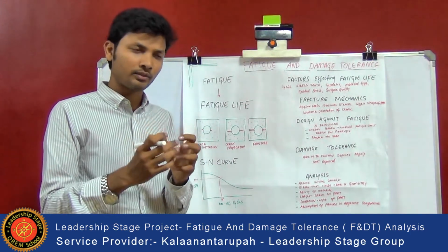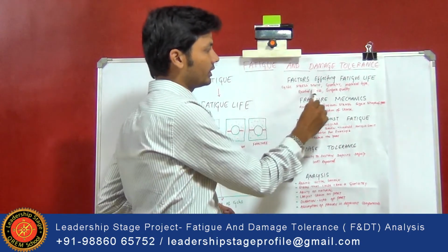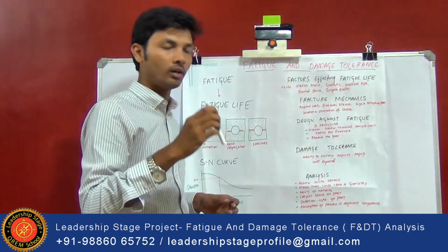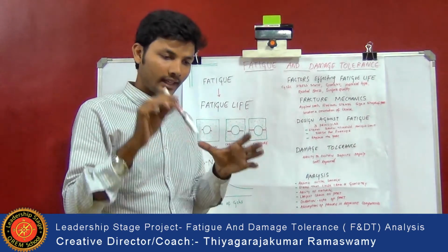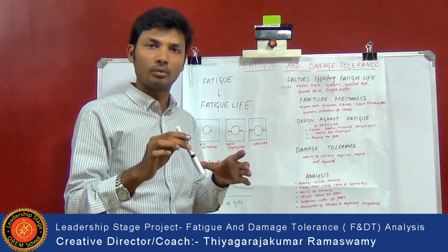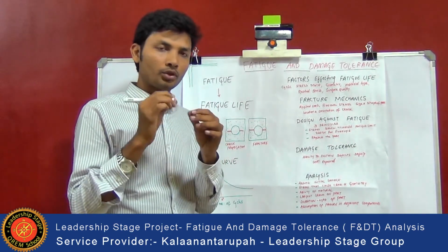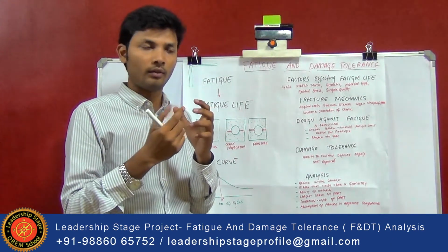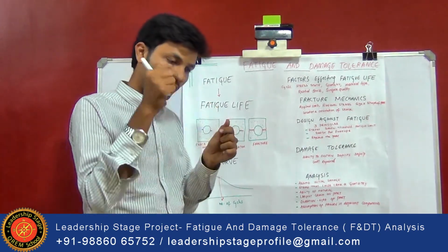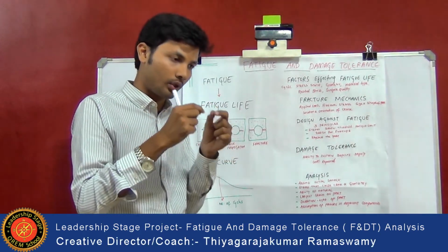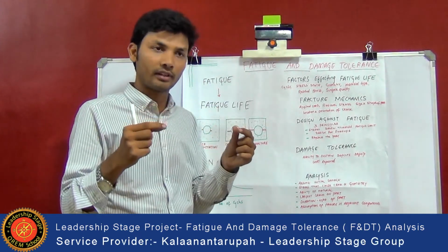What exactly are the factors which affect the fatigue life? Firstly, the cyclic stress state. It is nothing but cyclic loading and unloading of the loads on exactly the same position of the component. Initially, each fatigue starts with a microscopic crack, which is not visible to the eye. As the load keeps being applied on the component, that crack will increase its length, and eventually it will run to fracture.